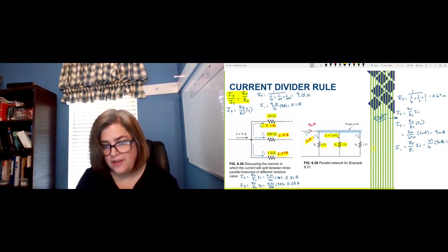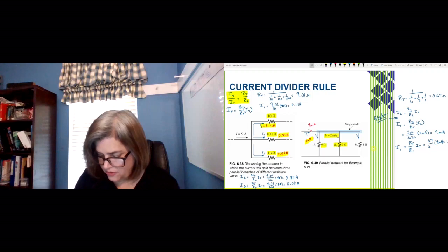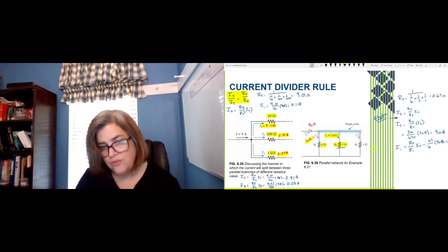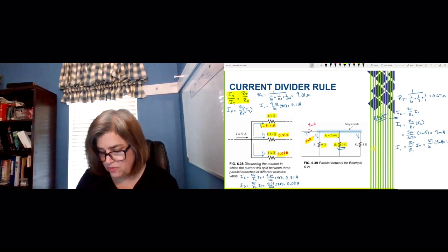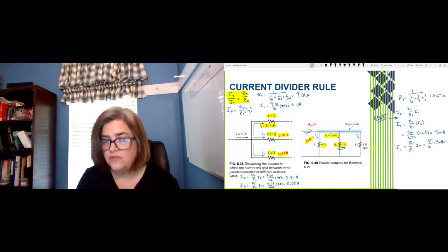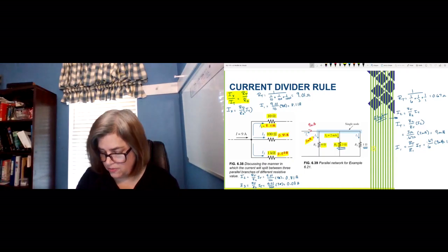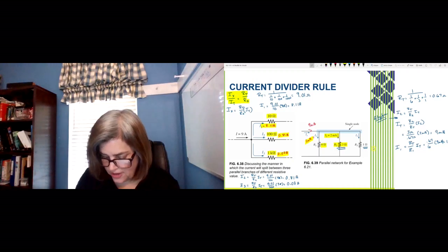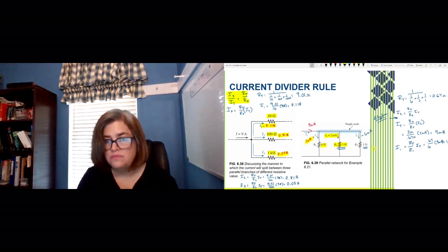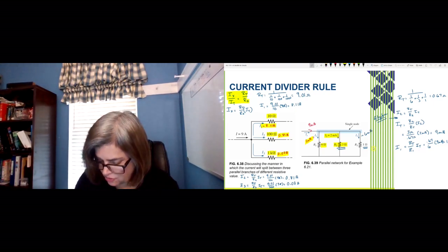So if that's the case, let's look at that 1 ohm resistor. Through a 3 ohm resistor we have 2 milliamps. If we have 1/3 of the resistance, how much current should we have through that resistor as R3? Well, if we have 1/3 of the resistance, we should have 3 times the current, 6 milliamps. Well, let's work it out and see if that's true.